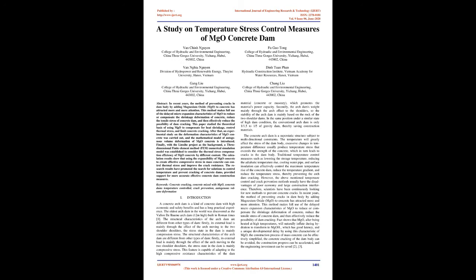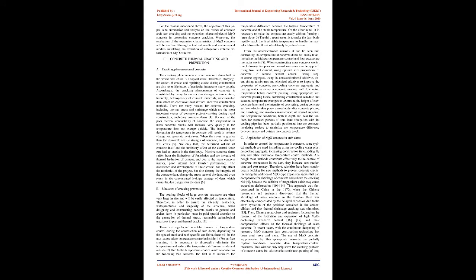For the reasons mentioned above, the objective of this paper is to summarize and analyze the causes of concrete arch dam cracking and the expansion characteristics of MgO concrete in preventing concrete cracking. Moreover, the evaluation of the expansion characteristics of MgO concrete will be analyzed through actual test results and mathematical models simulating the evolution of autogenous volume deformation of MgO concrete.